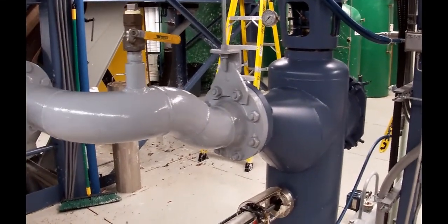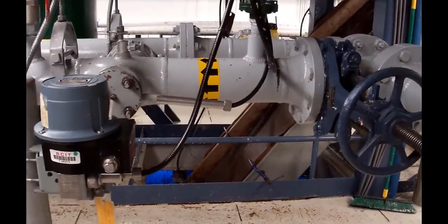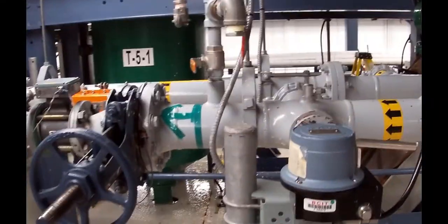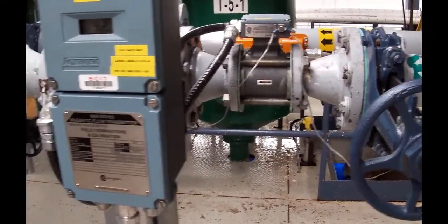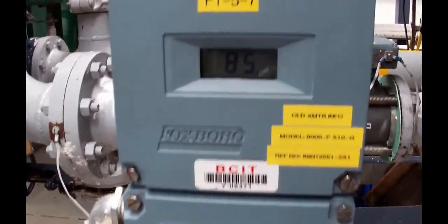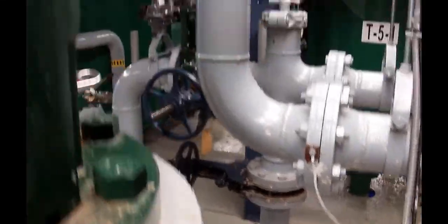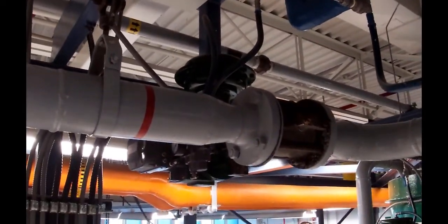The 3.5% stock comes along through this line here. There's a pressure transmitter located right there. And then it goes around through a mag tube. It's the part flow 5.7. And right now I'm showing about 89 gallons a minute. The flow then goes up through that line there, through this control valve, which is located right there.